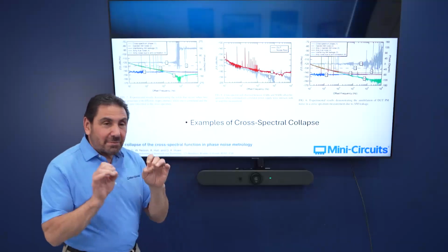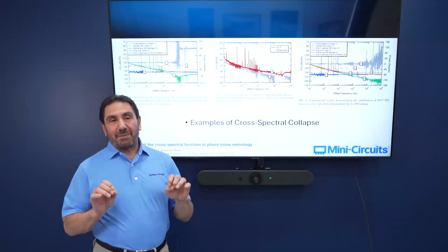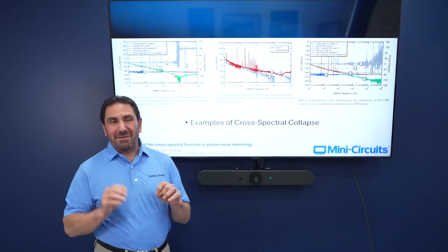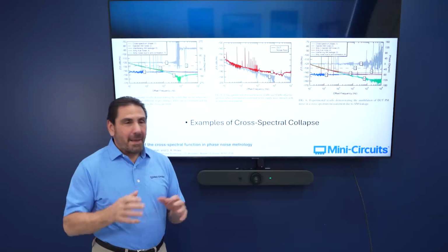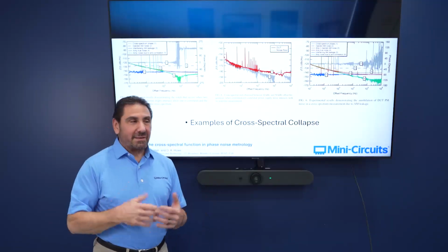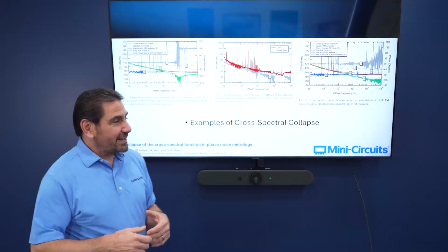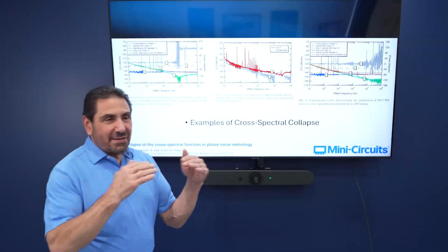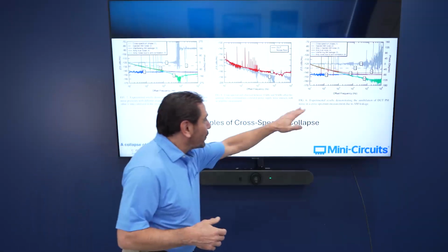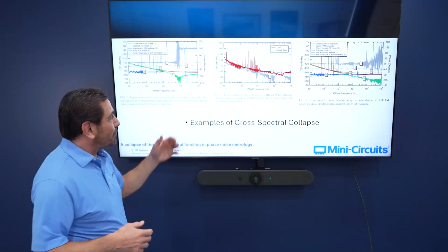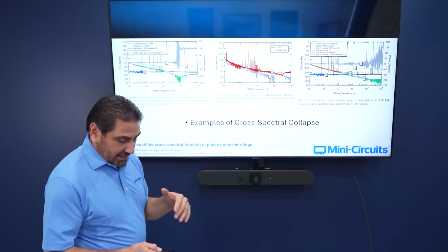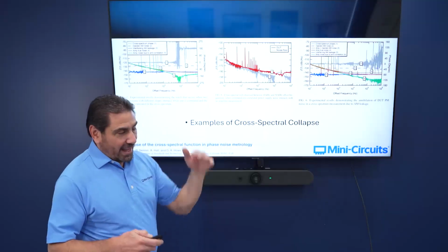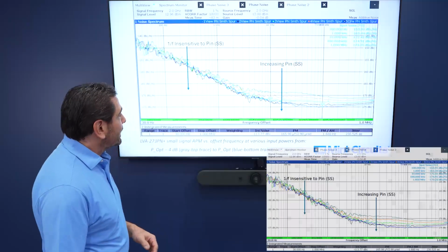And you change the setup a little bit, change the frequency a megahertz or so, change the power a little bit from the analyzer. Maybe it goes away, maybe it doesn't. Add some filtering on the DC. Try something, and if it changes much, it's probably one of the 2 phenomena, excess phase length or possibly this cross-spectral collapse. So now let's again go back and look at how high can we go.